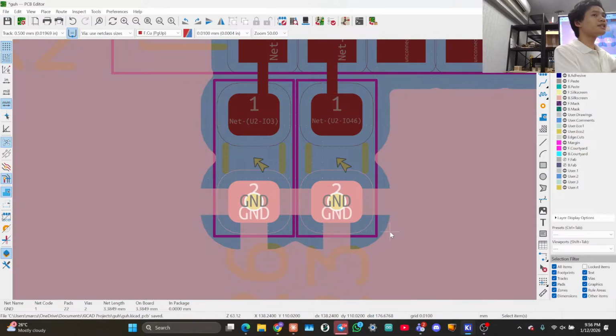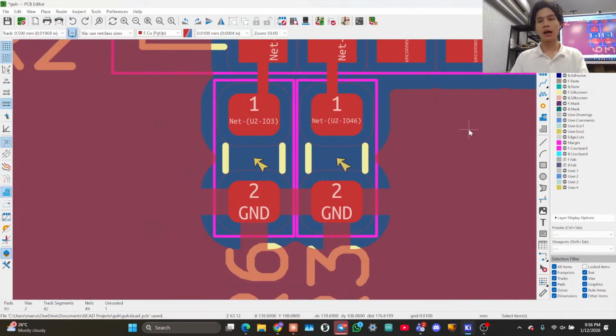So this will cause soldering issues. So via in pad technology caps the via off with copper, so it's not a tube anymore, and now the solder cannot run away. But this is an expensive process. So generally we avoid using via in pad. We always route out, and then we put a via outside the pad, and this avoids that problem.